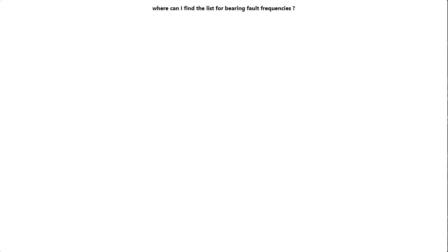Yep. Okay. So the answer to that question is that bearing fault frequencies can be found via our System 1 software in the configuration portion of that software. We have a database available that has thousands upon thousands of bearings that are already predefined. In some instances, if by chance there isn't a bearing in that database, we also have the ability to preload the characteristics that I talked about in the slide so that they can be automatically calculated for you.